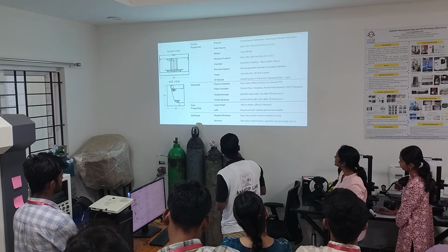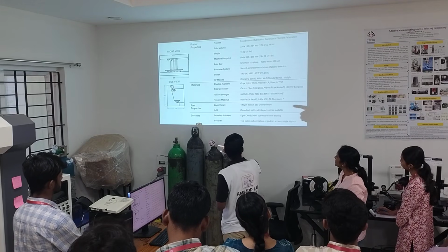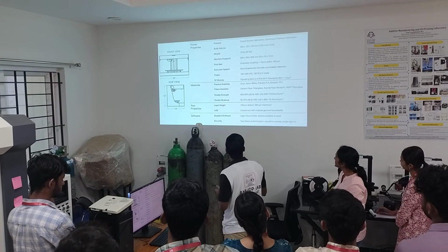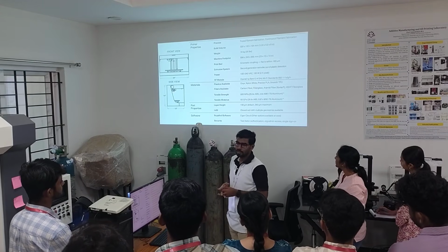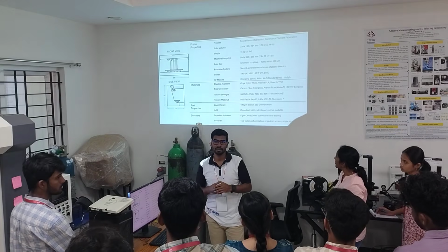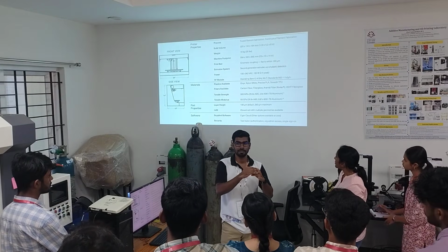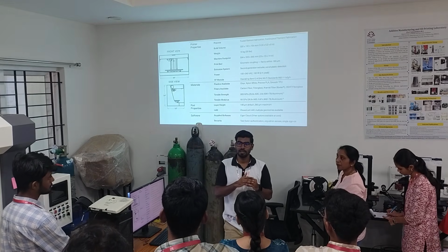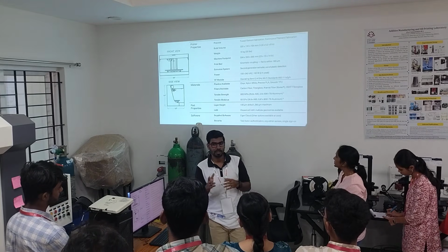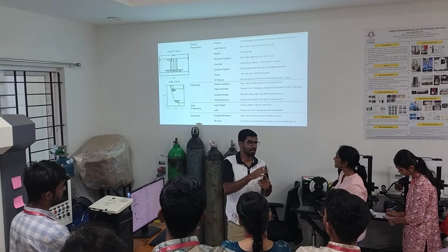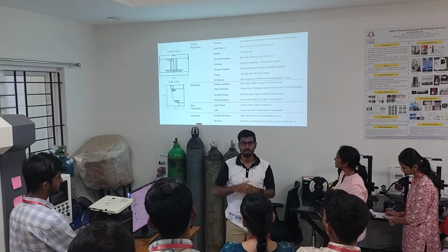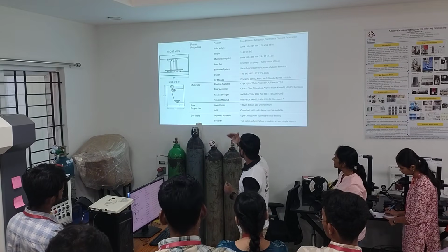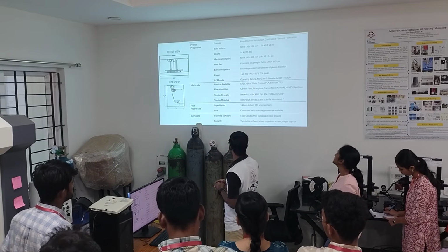Minimum layer height can be 100 microns, and maximum it can be 250. So I think in FDM they might have informed you what the minimum layer height of the FDM is. 0.12 millimeters. Sir? 0.125 millimeters. Basically it is 0.125, and some of the printers have the capability of 0.125 also. So this has higher precision compared to the FDM printers.